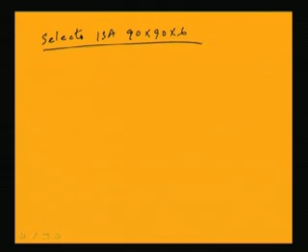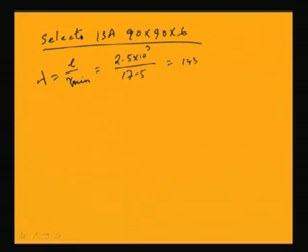So, if we select this, we will find out L by r minimum, that will be 2.5 by r minimum, this will become 143, which is less than 180. So, from slenderness point of view, the section is okay.